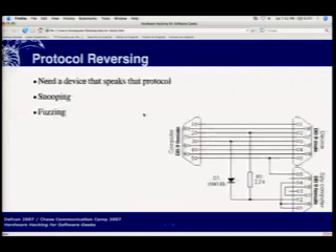If you have to reverse engineer a communications protocol between two devices, you have a few options. You snoop on the protocol if you have something that can speak it, so you can just watch as the two things talk to each other. The schematic that's up here is a serial sniffer. I believe this is a half duplex one, so it will only catch half of a communication. But this is for just ordinary RS-232 serial.